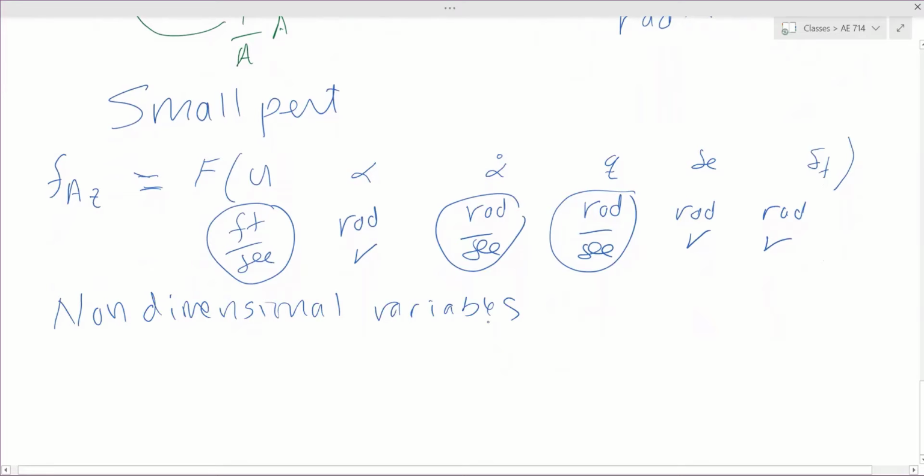And so we have to decide, well, what do we divide by to make it non-dimensional? And for velocities, the most obvious is to divide by the forward speed. So that makes it dimensionless. And how about v? Well, you divide by the forward speed. But hey, that's already beta. So that's nice. Our variable beta is actually a non-dimensional side velocity. And how about w? We'll non-dimensionalize that with respect to u1. But then we go, hey, for that one, that's just alpha. So alpha is a non-dimensional vertical velocity.